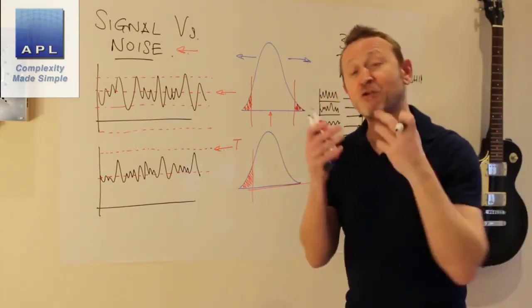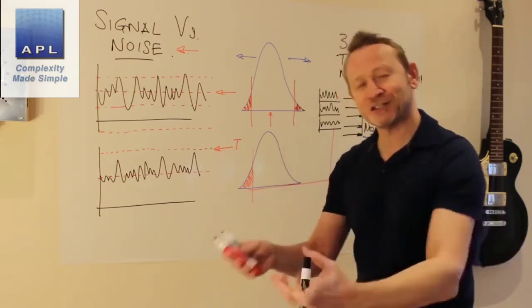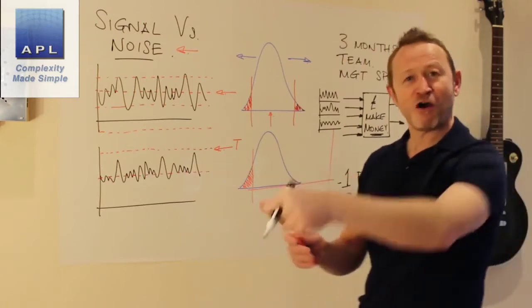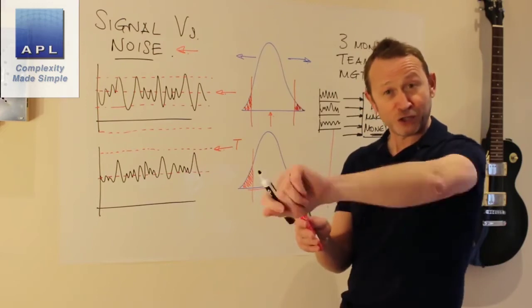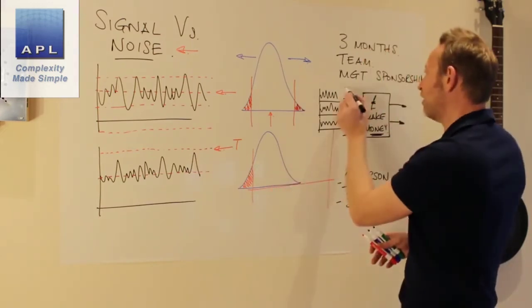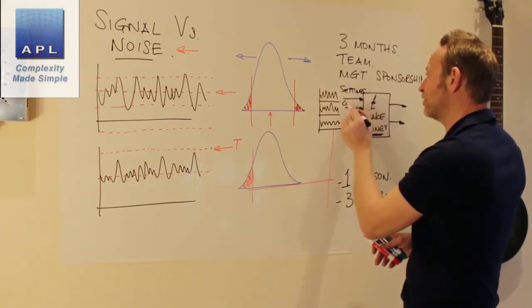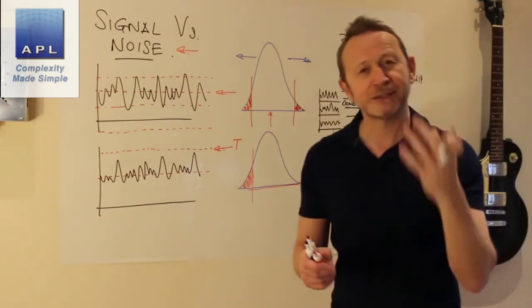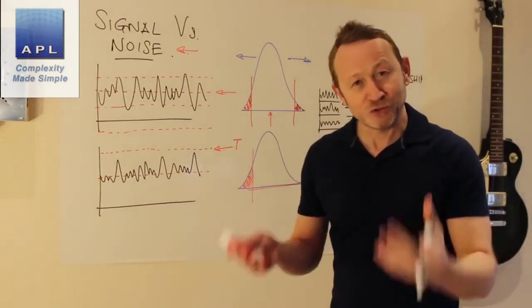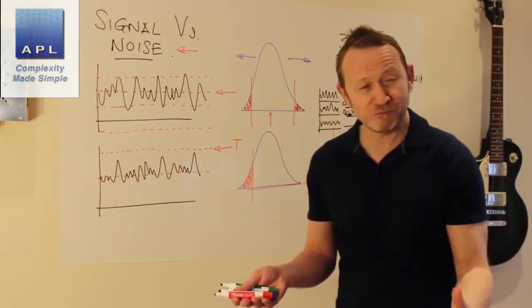They may be that you haven't provided the maintenance on your equipment, so the machine is behaving badly, and then the operator is trying to buy that bad behavior off by adjusting settings. So you have settings that are being moved. You have the condition of the equipment which is moving around. That's too much variability. You might also have poor quality material coming in here. Yeah, so you might be buying cheap material.